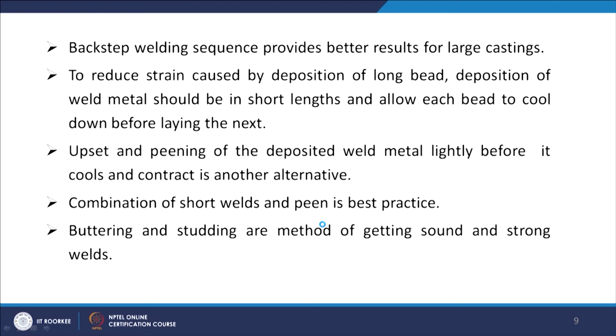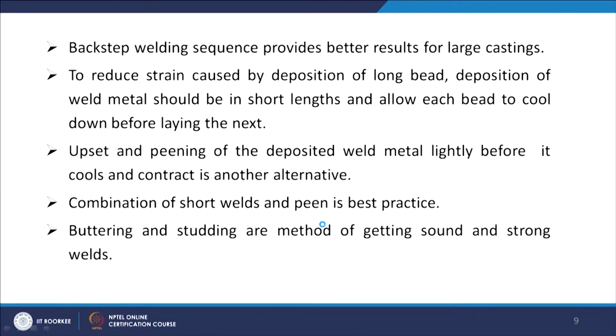That way you can reduce the strain caused by the deposition of a long bead. So, you deposit weld metal in shorter lengths, stop for some time, and then continue, because that way you will have a reduction in the strain. Upset and pinning of the deposited weld metal lightly before it cools and contracts is another alternative.